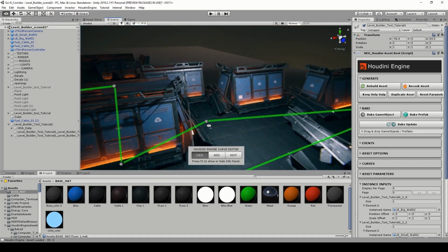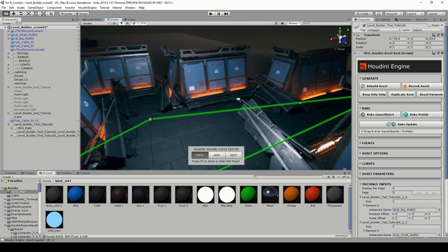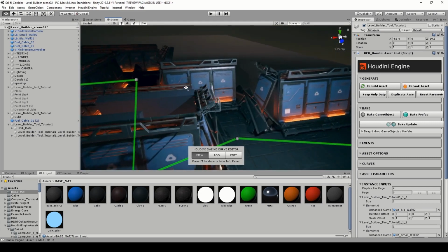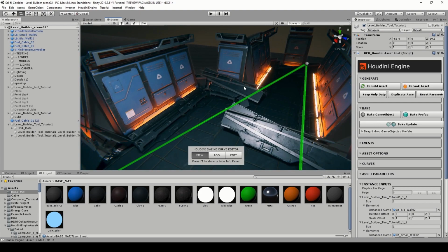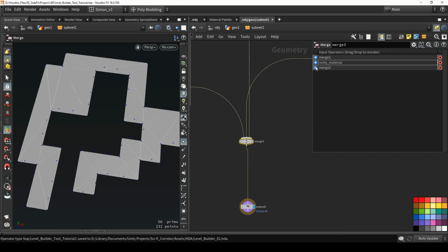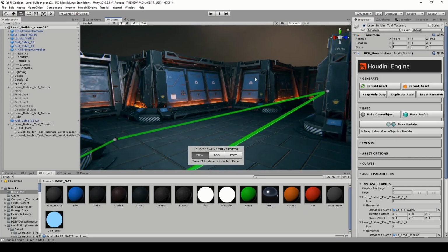So in here, I noticed that there is a chance that you might get a result like this. So what you can see is that everything before my floor geometry, the instances, worked correctly. Everything after the floor geometry, the instances got wrong. So that's just something that I noticed to keep in mind, that if this happens to you, just make sure you check the order in which things are going to be placed. So my floor comes last because it doesn't include instancing geometry. So when the order is correct, it should be fine.